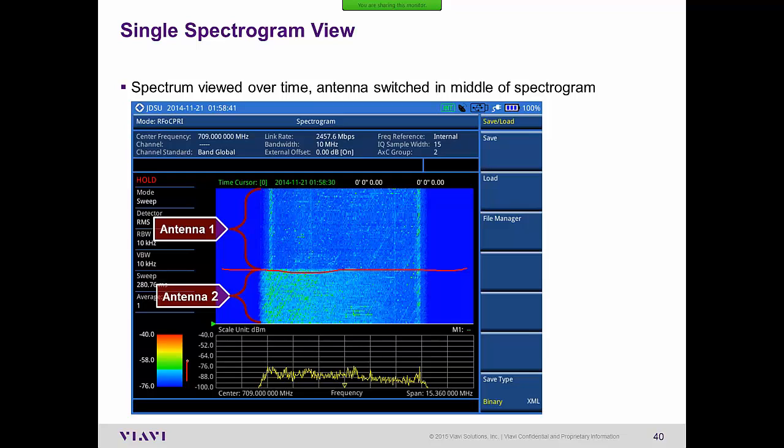The power starts to come up, and in the color chart over here at the left, you can see it changes from blue and starts getting into the green and yellow. So you can see very clearly on this spectrogram that you've got additional power on the other antenna that rises from right to left. It's kind of hard to see on a trace sometimes, because the trace will be jumping around based on mobile traffic. But it's very clear inside the spectrogram, in the color chart up above, what's going on.